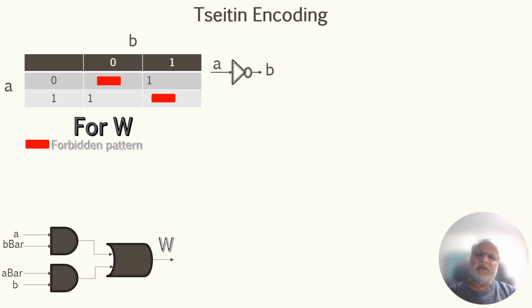Since the golden and revised designs which the formal tool will handle contain primitive gates, either inverter, NAND, NOR or AND gates or any such gate, how they will be interpreted by this Tseitin encoding will be analyzed in the coming slides. So here, each logic gate is expressed in a CNF form.